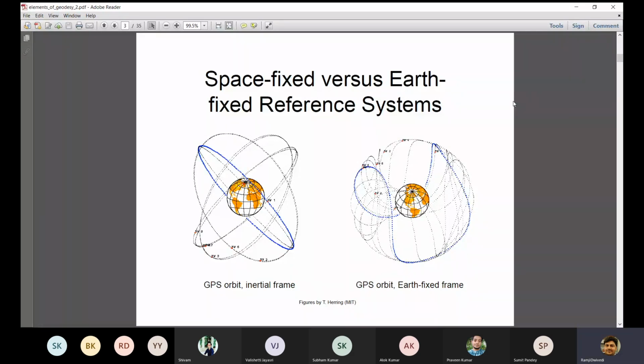If you do not know the coordinates of the satellite, you cannot work in GPS or GNSS. This whole concept fails. To work in this concept, the most important thing is that you know the coordinates of the satellite in the Earth-centered, Earth-fixed system, because you also want your coordinates in the same Earth-centered, Earth-fixed system. If you know this, only then does this technology work.